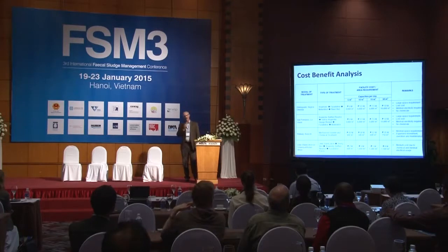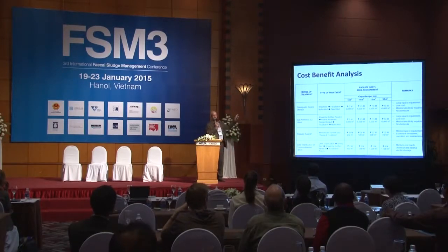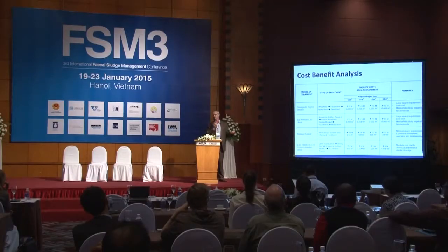We're not prescribing that any of the municipalities have to use lime, but what we wanted to do is a cost-benefit analysis for several different technologies, so we can really look at what the costs are and how they rate. So here we looked at an aerobic treatment system, an anaerobic system through lagoons, a hybrid system, which uses a combination of the two, and a fully mechanized system.